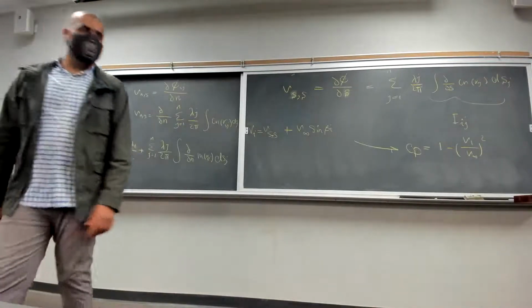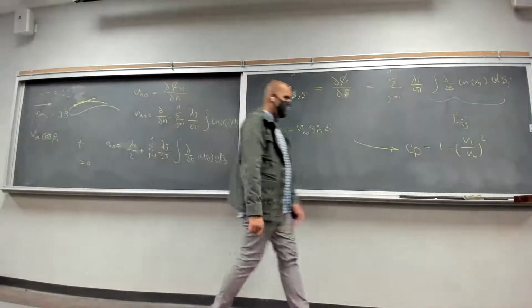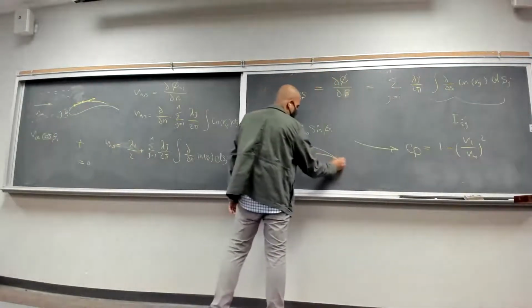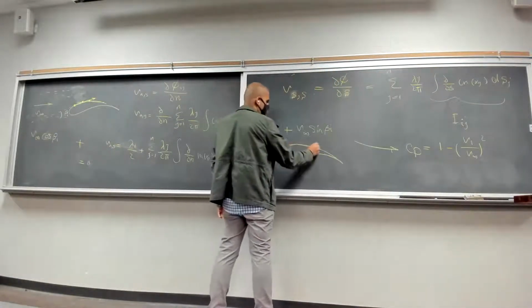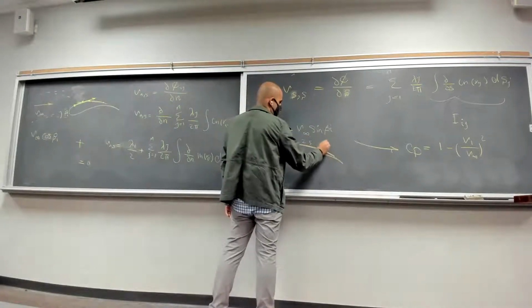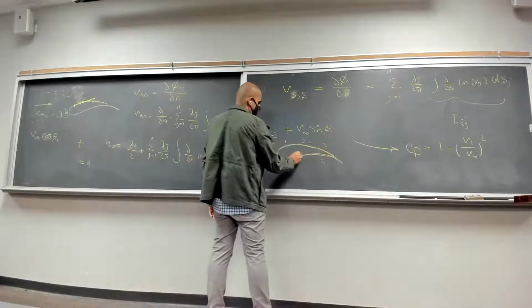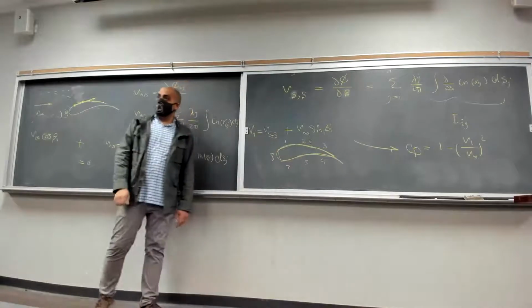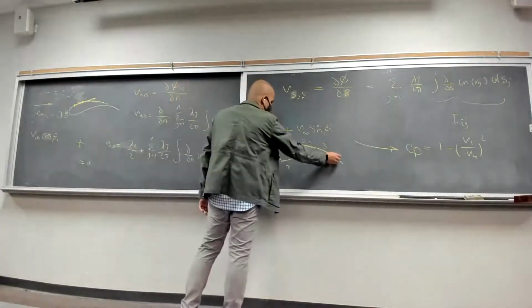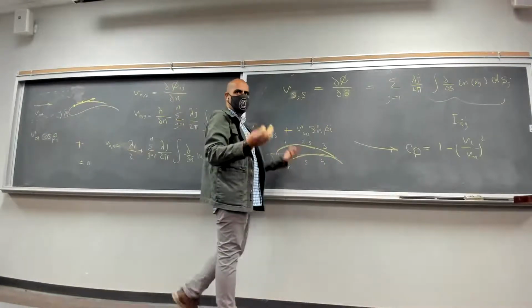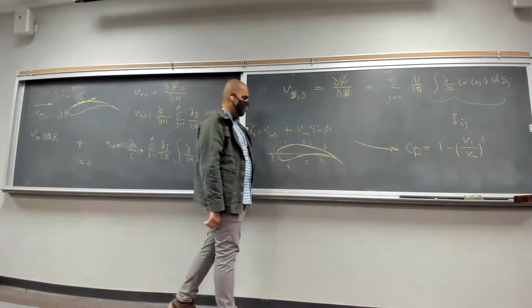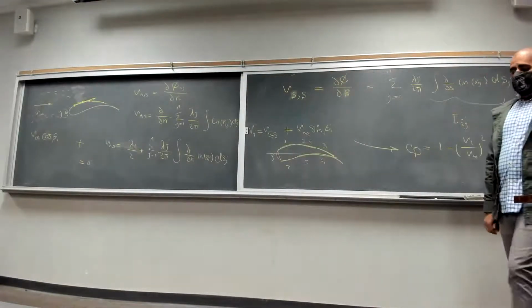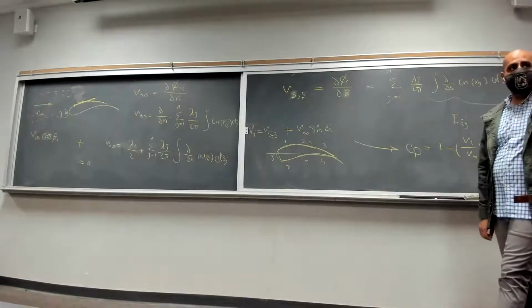No, there's no other summation. Your goal here is to find the CP, right? When you have the CP, let's say you have the value of CP here. Here you have the CP1. CP is like 2.5. CP is 3. CP is 4. CP is 5. CP is 7. And CP is 8. When you have the distribution, you can use the equations we already have, integral of CP lower, CP upper, dx to find the lift and drag coefficient.